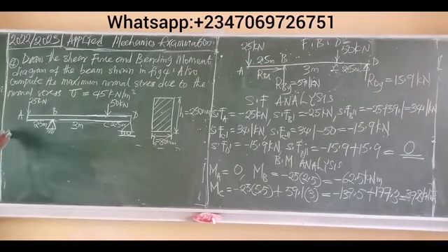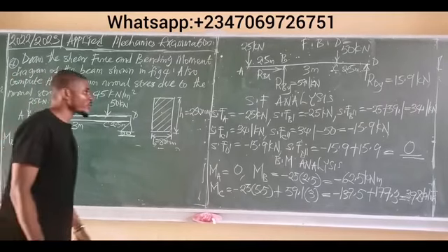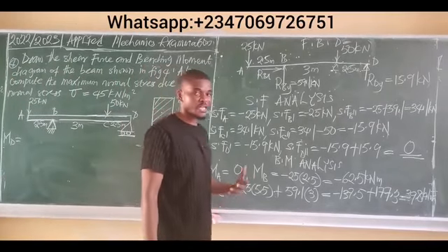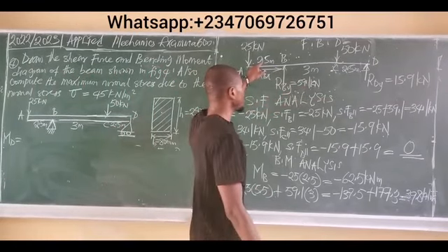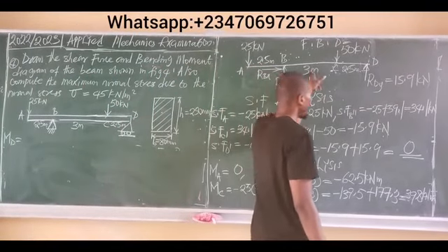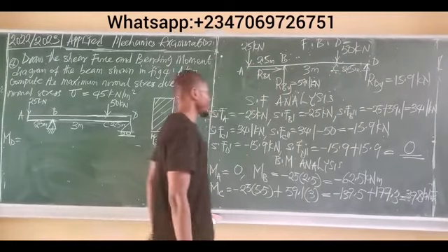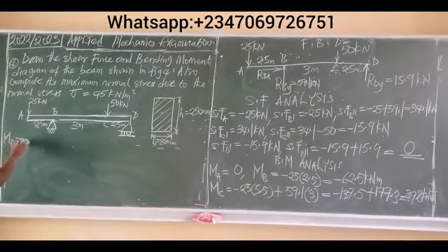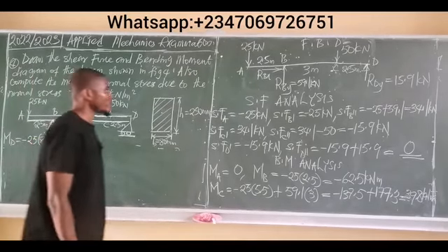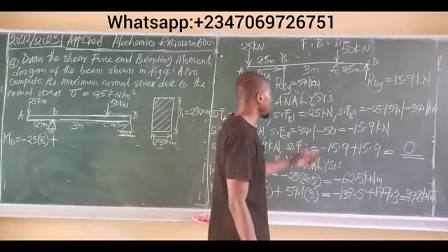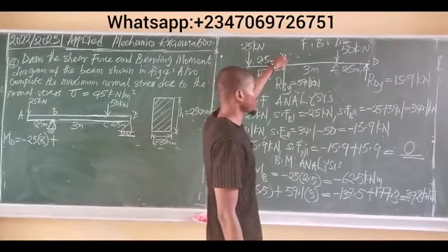So the moment at D is equal to, since this force is a downward force, it will produce a negative moment. The total distance it takes this force to get to point D becomes 2.5 plus 3, 5.5, plus 2.5, that gives us 8. So we have minus 25 times 8, plus. Now at point D we have the 59.1 kilonewtons force acting upward, so it's positive.